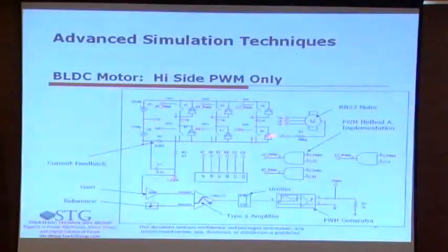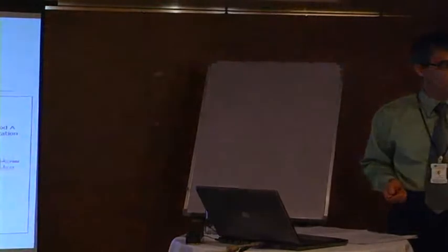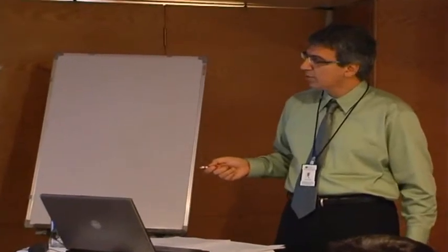And the bottom switches are driven by direct logic, A bottom, B bottom, C bottom. So you could essentially think about pulses and signals coming in, and we are directly driving the lower switches. So they are being driven by square wave or PWM? Square wave. So essentially square wave. That's right. The bottom is essentially square wave, and the top is being PWM.